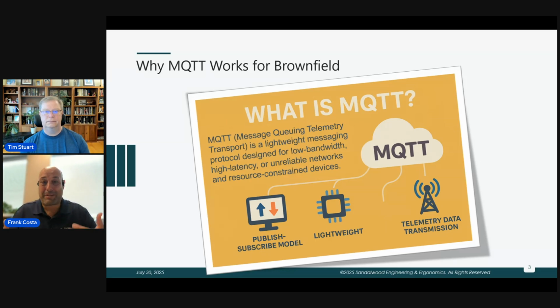So again, looking at that, what makes it good, MQTT being a lightweight pub sub messaging protocol, is that it sort of matches what you need. It decouples, like I said, the data producers from the consumers, and allows multiple devices to publish when things change, all to maybe the same topic or mailbox, or to separate ones.